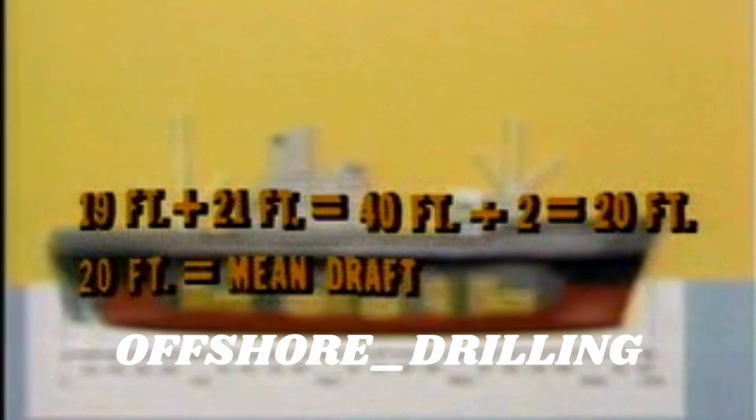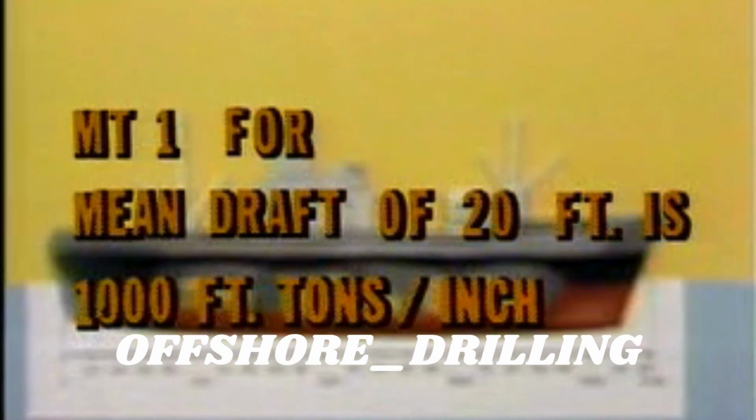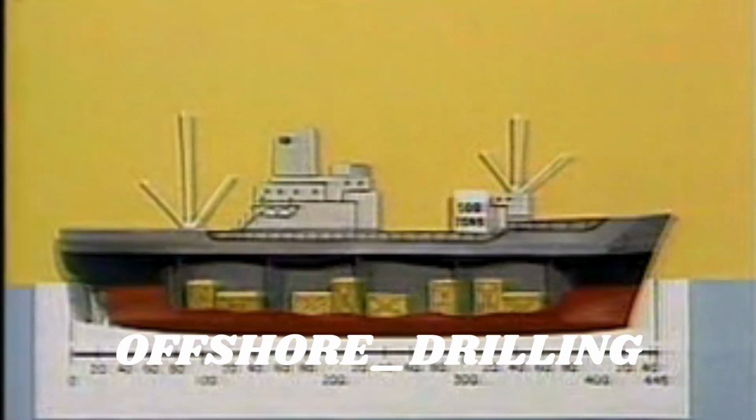the tons per inch immersion and the MT1, moments to trim 1 inch. For the purpose of this problem, assume that after consulting the deadweight scale or hydrostatic curves, we find that the MT1 for a mean draft of 20 feet is 1,000 foot-tons per inch. Now, if we shift weights without adding or removing weight, we will change only the trim without changing the draft.